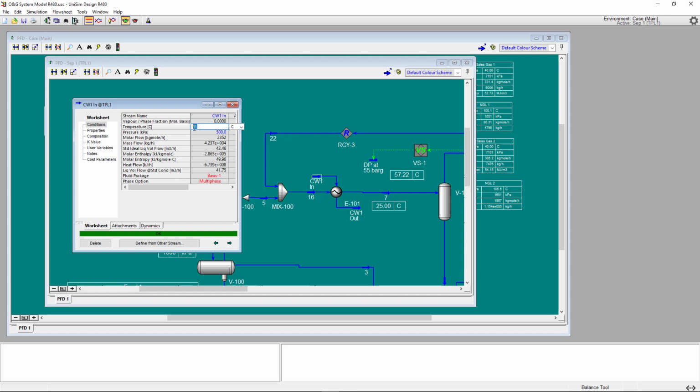I can also choose a unit type. So if I wanted to enter in a different unit, I could pick in there the unit I would like, and it would use that instead of the current display unit, which is centigrade. Instead of pressing F2, actually, if I click on this small bar on the left-hand side, I get the same effect. I can edit and choose the units there. So that's another use for the F2 key.